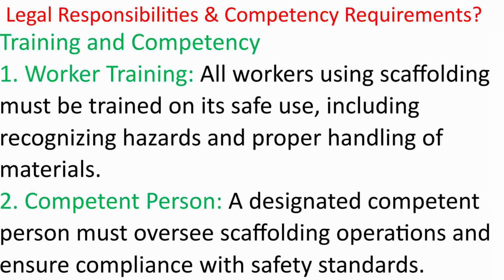Training and competency. 1. Worker training. All workers using scaffolding must be trained on its safe use, including recognizing hazards and proper handling of materials. 2. Competent person. A designated competent person must oversee scaffolding operations and ensure compliance with safety standards.